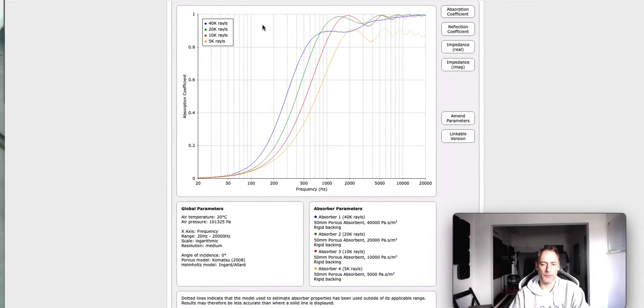So as I was saying, and not to go further into this discussion, the blue line is the denser material, so this would probably be mid-density rock wool. The green line would be light density rock wool, or probably an acoustical foam. And the two other curves would be PET materials with different flow resistivity.